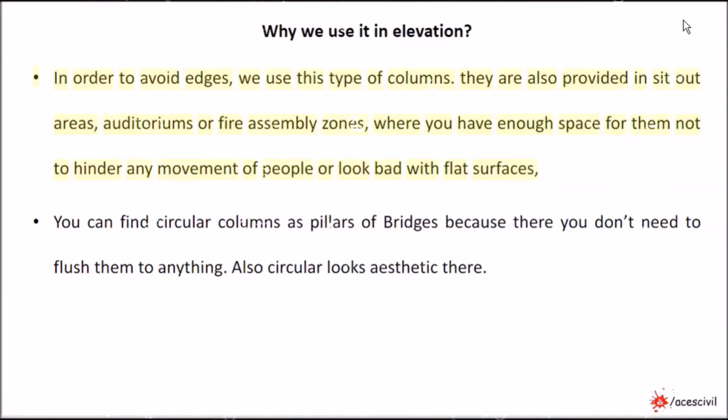They are also provided in sit-out areas, auditoriums, or fire assembly zones, where you have enough space for them not to hinder any movement of people or look bad with flat surfaces. You can find circular columns as pillars of bridges because there you don't need to flush them to anything. Also, circular looks aesthetic there.